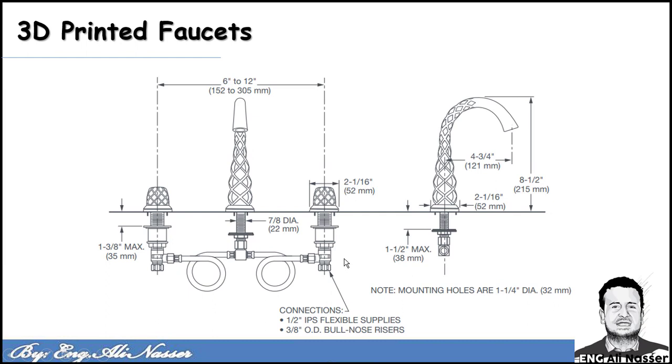Before we start, let's think about our methodology, how we can start to build this geometry. In my opinion, we can firstly build the main body, the outer body, using features like sweep or loft or boundary.